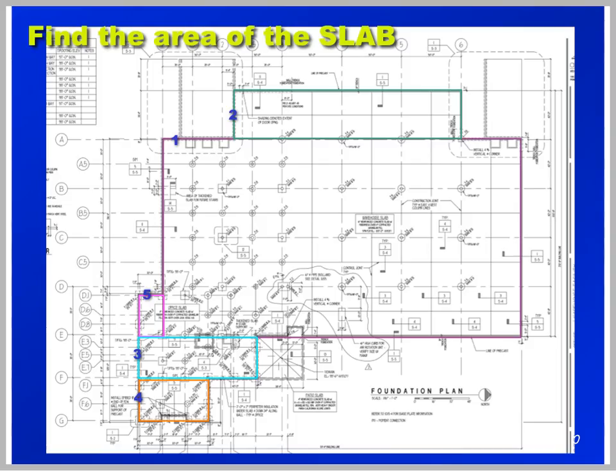So how does this apply to construction? Well, let's just say we needed to find the area of this building right here. What I do is I start breaking things down into shapes. We have a shape here, which we can easily find dimensions. We have a shape here. We have shape number 3 here, number 4 right there. These little pieces, 5. I guess that's all the shapes.